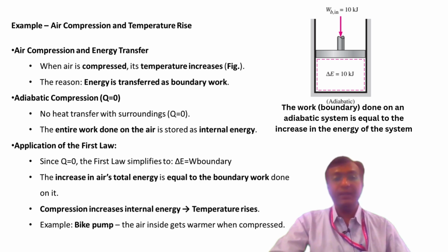As we know, when air is compressed, its temperature increases. This phenomenon is a direct result of energy being transferred to the air in the form of boundary work. Boundary work refers to the work done on or by a system as its volume changes. Now, in case of an adiabatic compression, the heat transfer becomes 0. Therefore, if we assume for our simplicity that the compression process is adiabatic, meaning there is no heat transfer between the air and its surrounding.